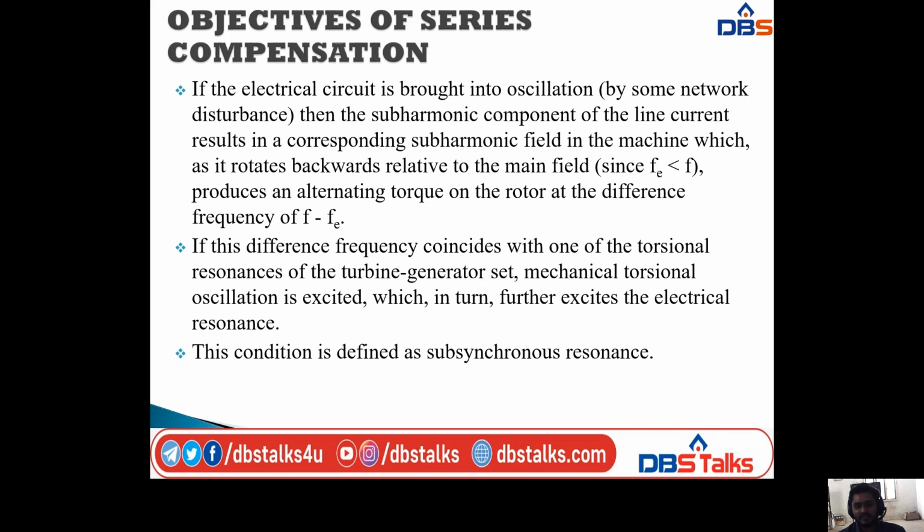If this difference frequency coincides with one of the torsional resonances of the turbine generator set, mechanical torsional oscillation is excited, which in turn further excites the electrical resonance. This condition is defined as subsynchronous resonance.